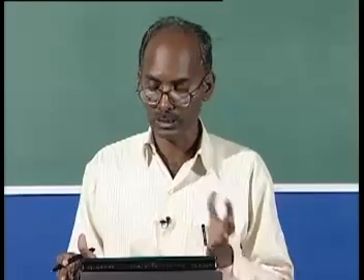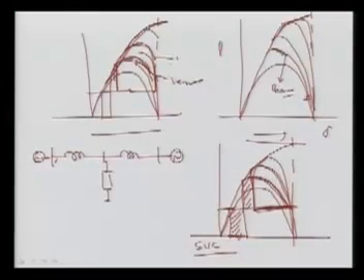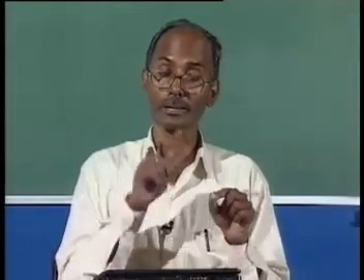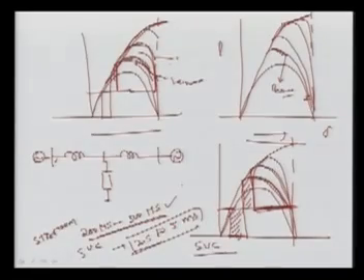It's very simple to control, very simple to manage, and already we have all these things. If you see the time response, the STATCOM time response is from 200 microseconds to 500 microseconds. This is for STATCOM. However, for SVC it is from 2.5 to 5 milliseconds. So STATCOM is very fast compared to SVC as well, because we have converter-based technology. Here we have the inductors. If you are switching here, you will require some time, so this time is in milliseconds, so it is also very fast as well.